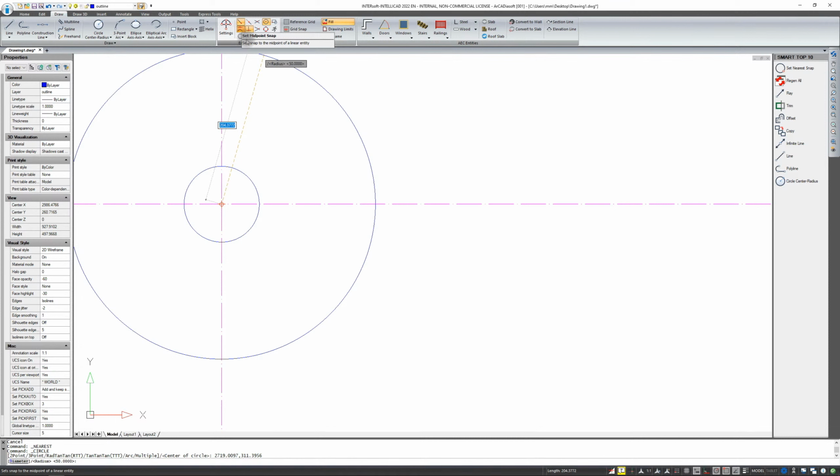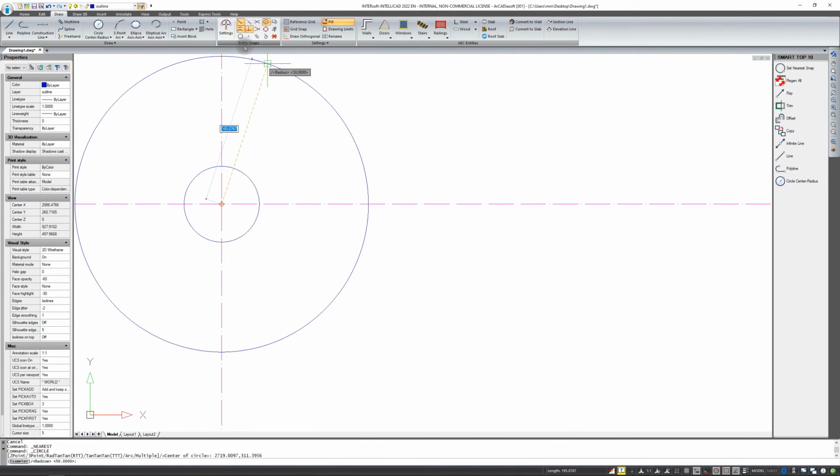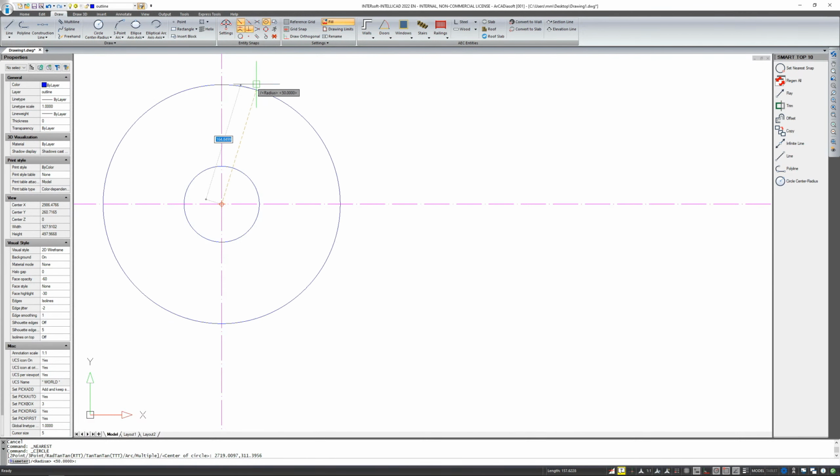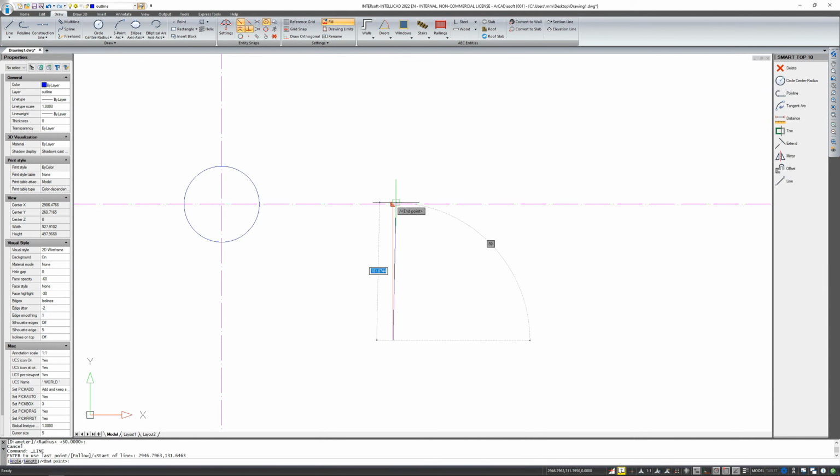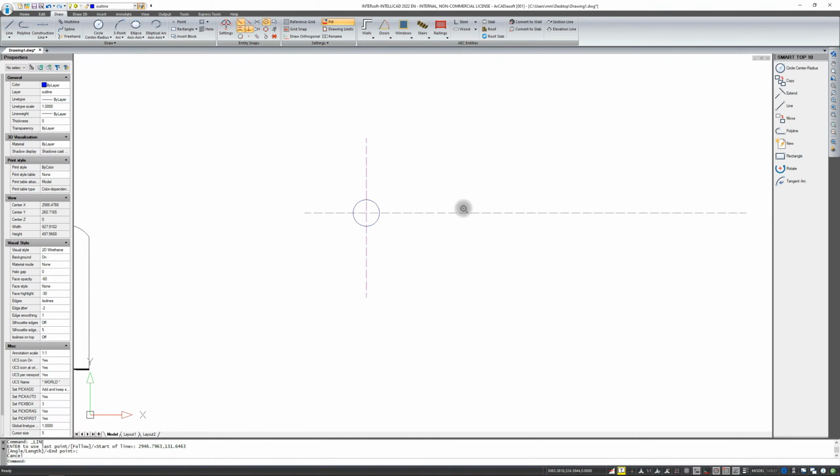You also have an intersection here, but I have already mentioned the perpendicular point. Remember that the perpendicular point is always the second point of your line. So you do not start from the element and draw perpendicularly. You only show the point outside the line, and it finds the perpendicular on the element.